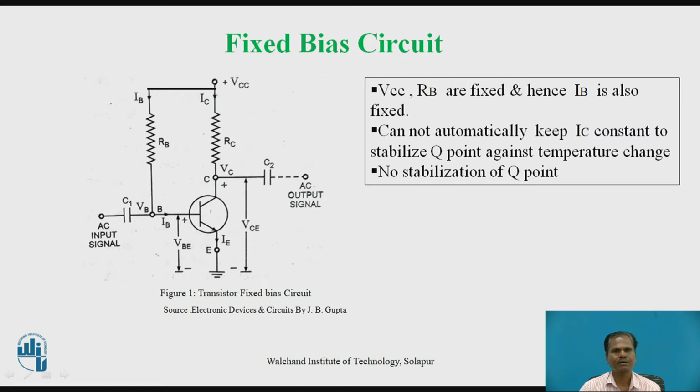Amplifier is operated on a single DC power supply. So, both the junctions of transistors are biased using a single positive DC voltage power supply VCC as far as NPN transistor is concerned. So, the minimum voltage required to forward bias a base emitter junction, that is the cut-in voltage, and to set a desired value of base current IB and corresponding collector current IC, the base biasing voltage is obtained using the same DC power supply plus VCC.